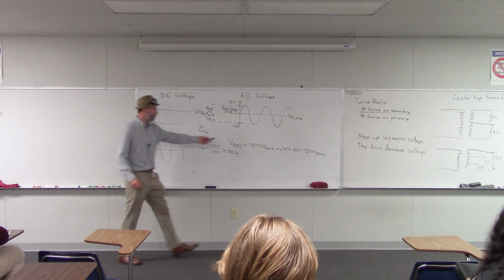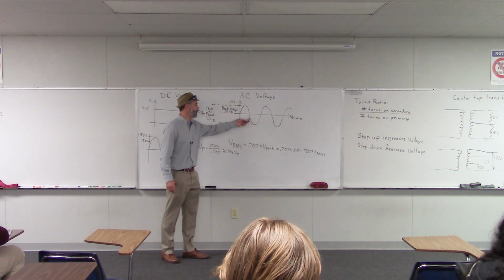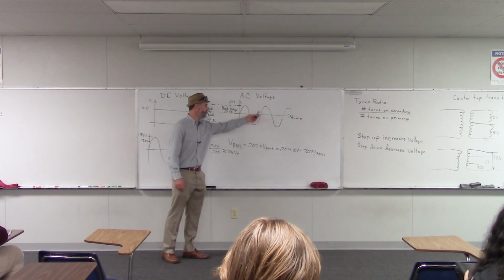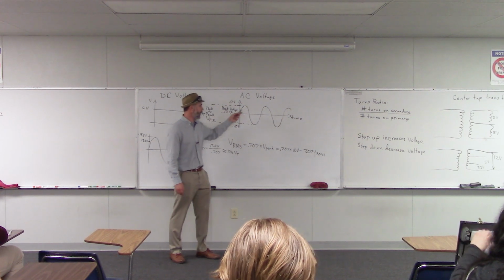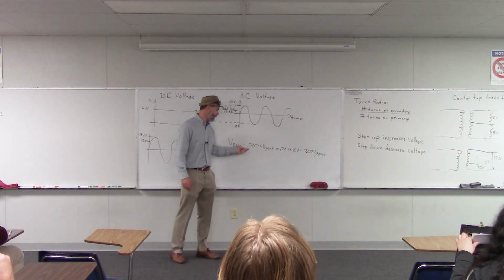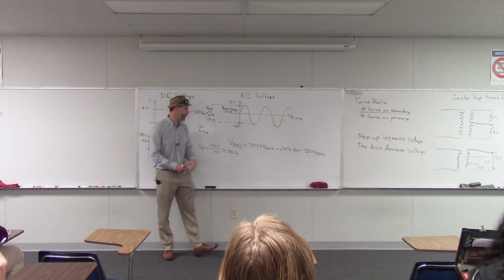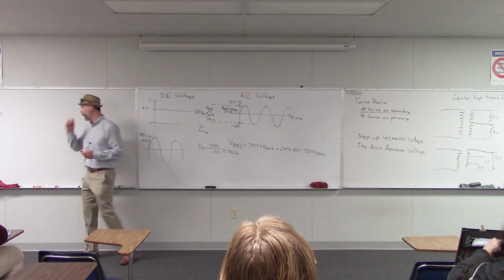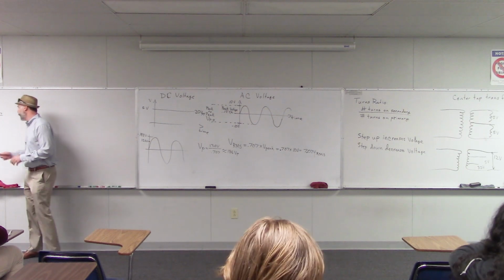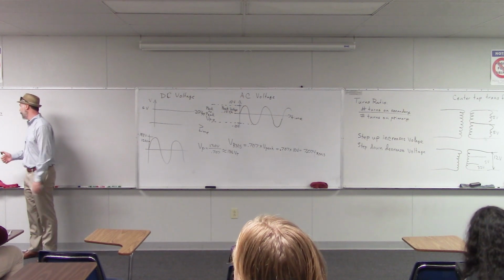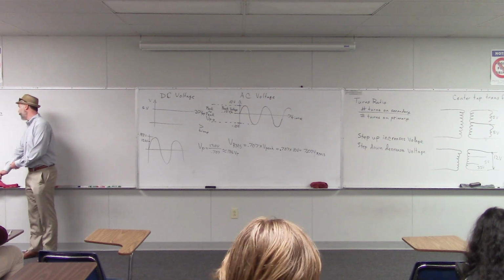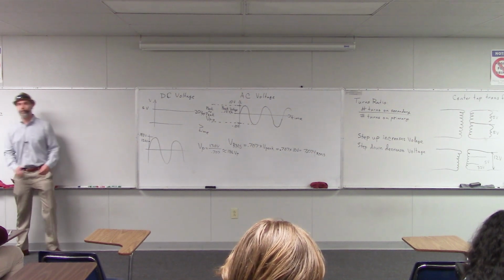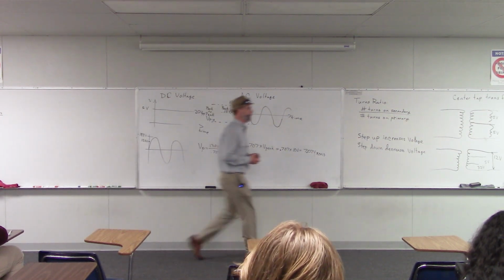And this conversion is true for sine waves. If it were a different type of wave, like a triangle wave or a square wave, you would have to use a different conversion factor here. But this is for sine waves. All right. So that's what I wanted to say about voltage measurements. So then let's go on and do a preview of today's lab.